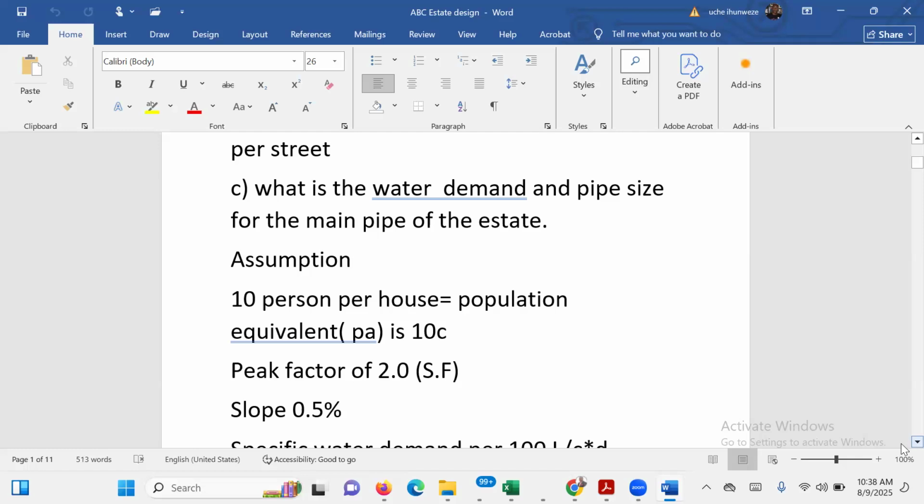The idea, gentlemen, is that when you lay these pipes on the ground and you make a mistake, retrieving them is a disaster. I have seen where people spent 200 million naira and the consultant did a bad job, and everything just went down the drain. So that is why, as an engineer, you must not play with your safety factor. Not to talk of the other errors, other contingencies that are inherent in safety factor. Safety factor is where you hide your errors or your uncertainties. You know, it's a form of a sensitivity analysis factor.